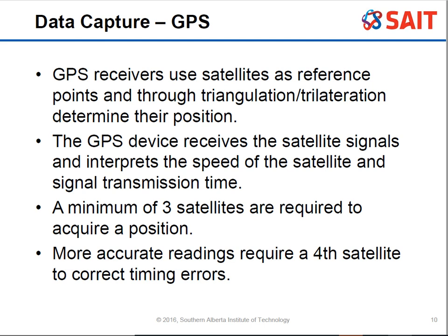So for the most part, the quality that you have in either a handheld GPS or a mapping quality GPS or your cell phones is generally good enough for a lot of the thematic stuff that you would be doing. So if you're going to be using a handheld GPS, there are a few things you need to watch for while you're collecting data.